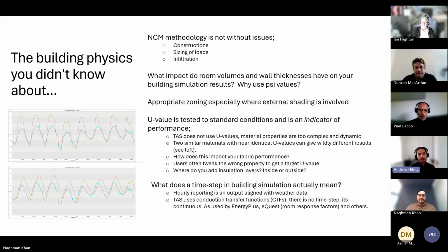So what we're really saying here is it's important to remember that when you assign a zone to a space, a zone should represent a homogeneous parcel of air, where you're not experiencing vast differences. For example, if you zone a room near a window, you'd expect the temperature near the window might be higher, because it's receiving daylight and more solar gain. That area is not necessarily representative of the whole space. And this particularly applies to atrium zoning as well.